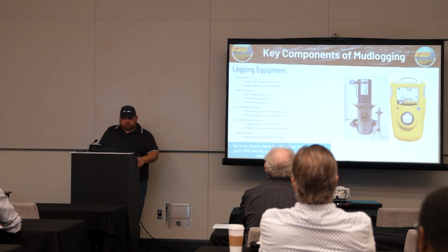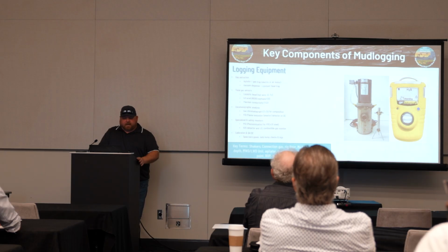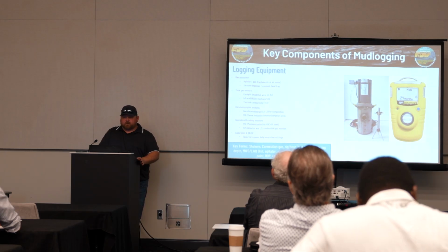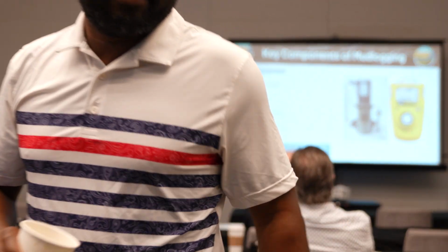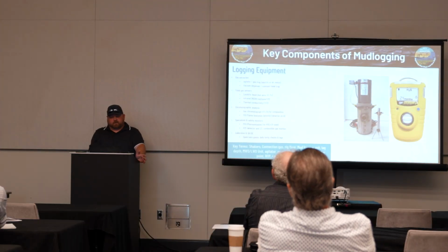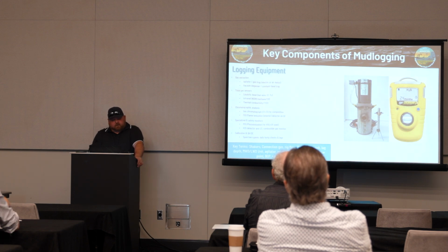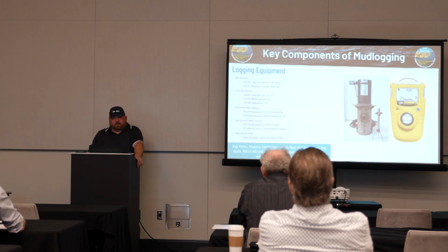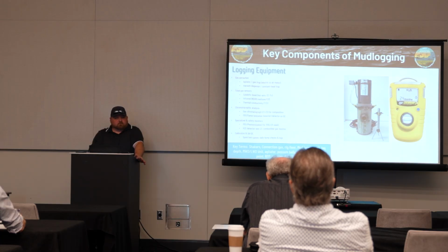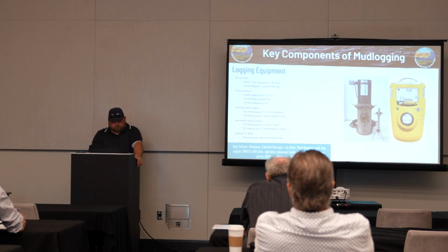Chromatograph analysis. Typically, a gas chromatograph uses a TC filament for C1 through C5 combustion. And then a lot of people go to the FID nowadays. That's old school stuff that I think has been around since the 80s or something like that. It's been going on for a long time. It's gotten a lot smarter. It'll read C1 through C7 on most of them.